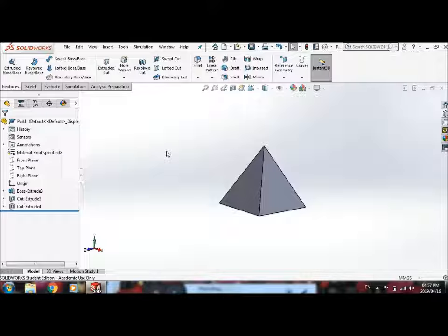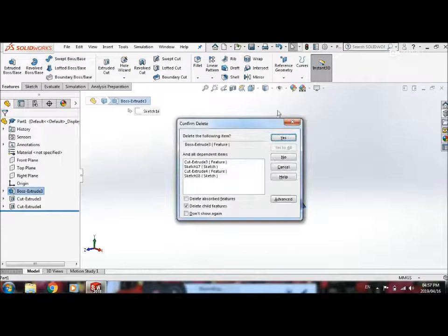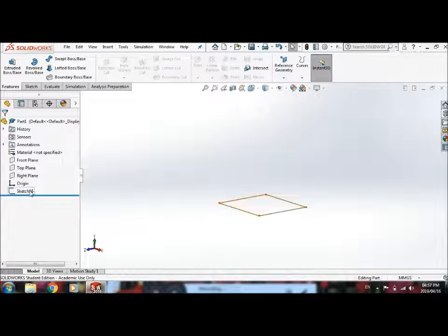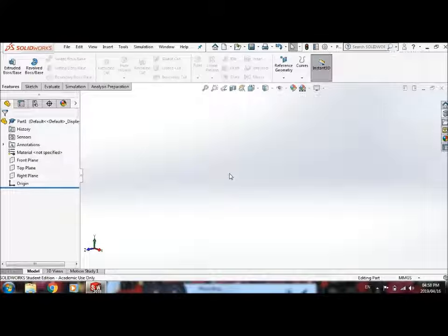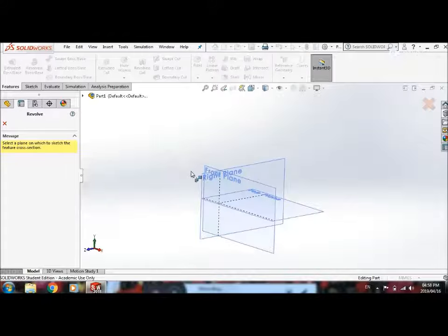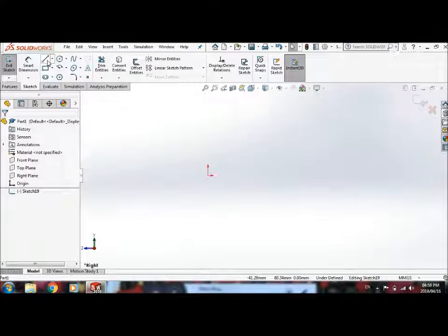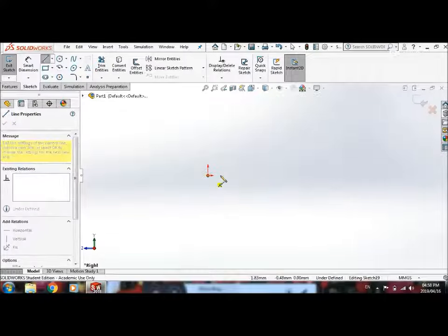Mag wheel. Yeah, yeah. A mag wheel next, coming right up. So one property of a mag wheel that is quite easy to identify, or feature of the shape, is that it's symmetric about the rotational axis, or a big part of it is, the outside part, the round part. So what I'm going to do is start with the revolved boss or base, select the plane, and then let's start.